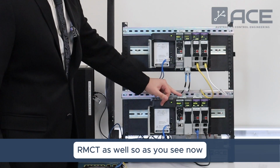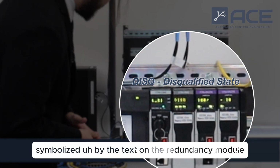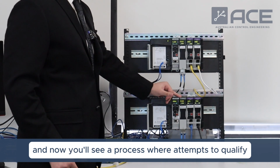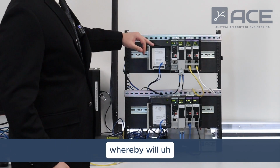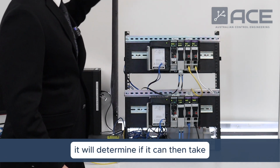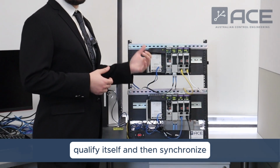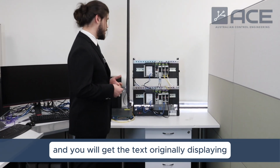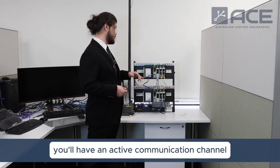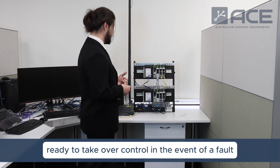So as you'll see now, the original PLC is now in a disqualified state, symbolized by the text on the redundancy module. And now you'll see a process where it attempts to qualify, whereby it will detect the modules and the firmware revisions in the primary PLC. As a result, it will determine if it can then take control over that system, qualify itself, and then synchronize, and you'll get the text originally displaying when we started. And at that point, you'll have an active communication channel cross-loading, and the redundancy system will be ready to take over control in the event of a fault.